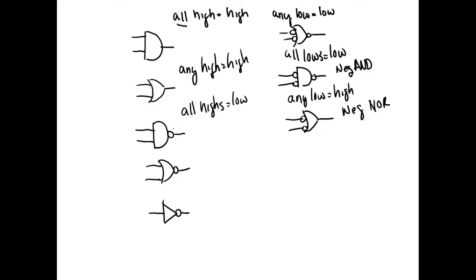So why do we call this a NAND? Not because it's got a bubble on the output. That's not why it's a NAND. It's a NAND because the inputs are high active and the output is low active. So is that the same? No. So don't get that bubble on the output as being NANDs and NORs and that kind of stuff, right? You understand? What we're looking at is the difference. If they're the same, it's going to be an AND or an OR. If they're different, it's going to be a NAND or a NOR. But for some reason, people grab on that, unfortunately.